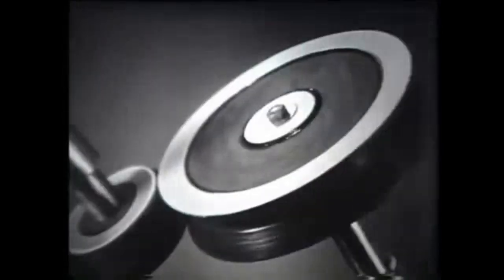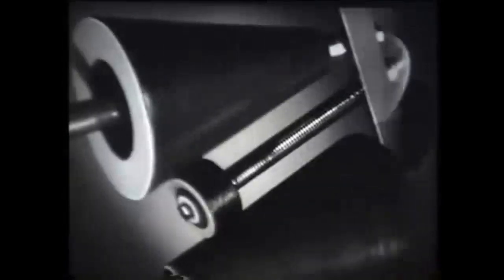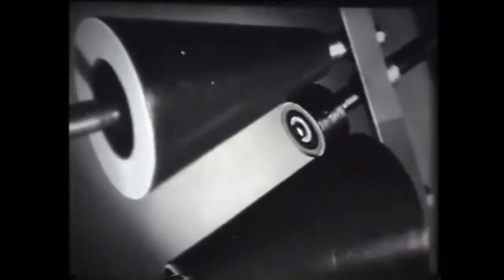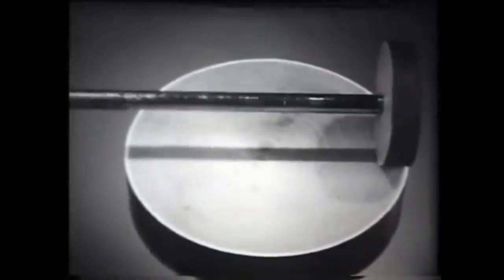The advantages of friction gears: simplicity of design, smooth motion transmission, noiselessness, stepless speed change. And the disadvantages? The variability of the gear ratio due to slippage, high pressure on the shaft supports and significant wear of the rollers.